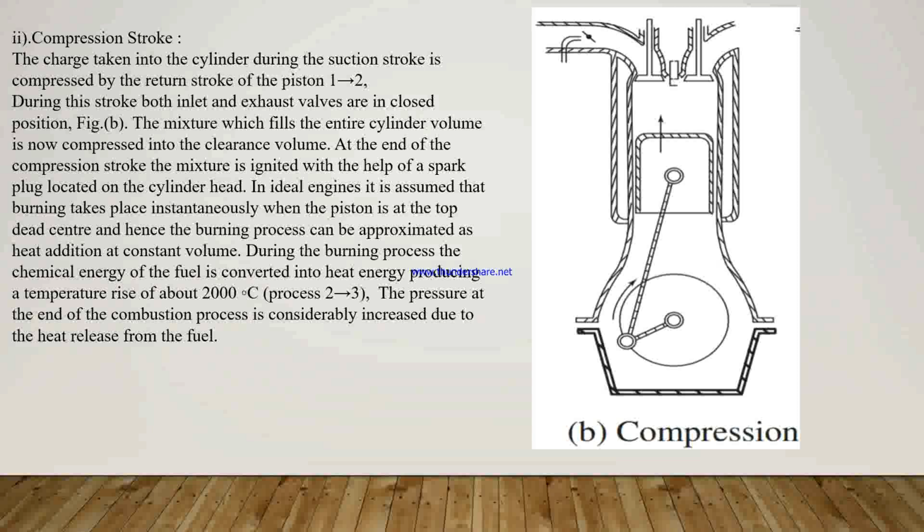At the end of this compression stroke, the mixture is ignited with the help of the spark plug. Here the spark plug is located. In ideal engines, it is assumed that the burning takes place instantaneously when the piston is at the top dead center, and hence the burning process can be approximated as heat addition at constant volume.